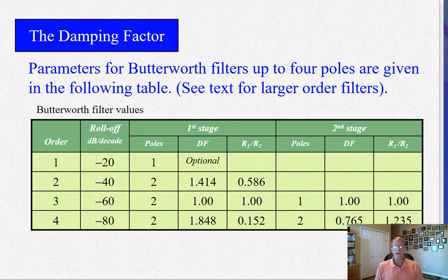So you're never going to have to determine mathematically the damping factor for a particular filter characteristic, because those are given to you in tables. They're Bessel tables, okay? Bessel function tables, which are really a mathematical monster, which we don't deal with here. We don't need to. But the Butterworth response is determined by the damping factor and the order of the filter.